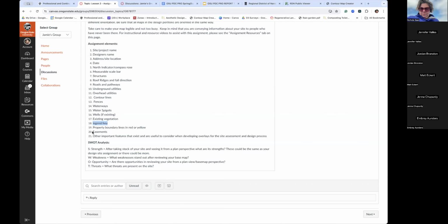Yeah, so easements are very important. Often we find those in city or urban centers, and again, they may be giving the municipality or the town access to sewer lines or water lines, so you'd want to be very aware of those and not be planning for anything permanent to sit above them.